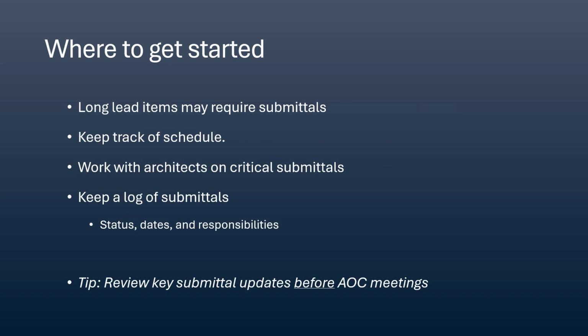All right, and things to consider when we're working on submittals. If we're just starting on a project, it's day one, you want to know which submittals to do first. Look at the project schedule and look at long lead items. Maybe reach out to your subcontractors and figure out what the long lead items are for your project.